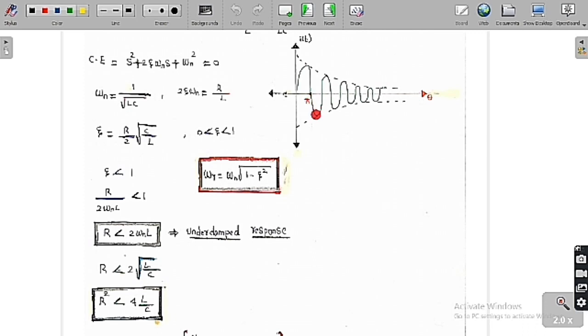Therefore we can say that the thyristor is going to open after omega t is equal to pi. So after omega t is equal to pi, it is going to turn off. Or simply, we have assumed that the latching current is equal to 0, or the holding current is equal to 0. So here i(t) tries to become negative, but at pi the thyristor is going to become open because the current wants to be negative.